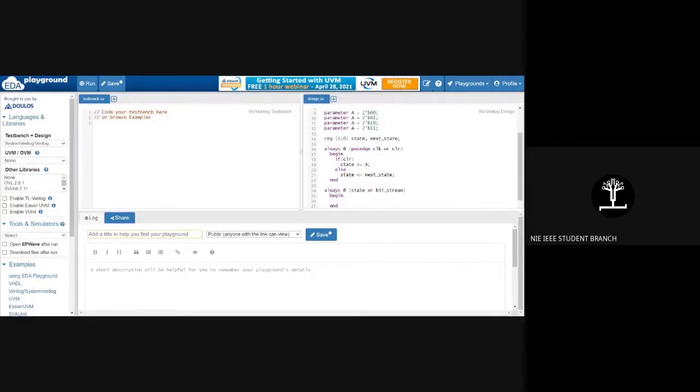So I have now, I'll use case statements to check each case. Whenever it is at some state, what should happen next? If it is in B, then what should happen when it goes to C? So that's how I do it. I'll begin with the case statement, and the case statement will depend on the current state. And yeah, let's begin. What's my first state? If the state is A, then what is supposed to happen?